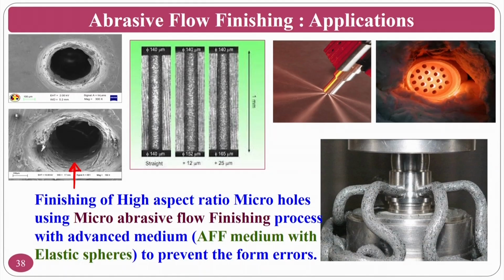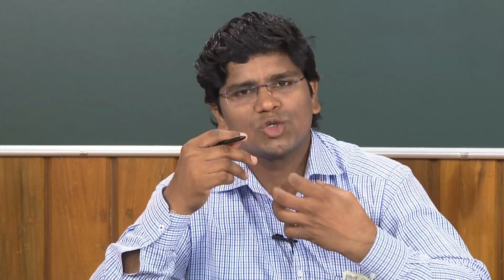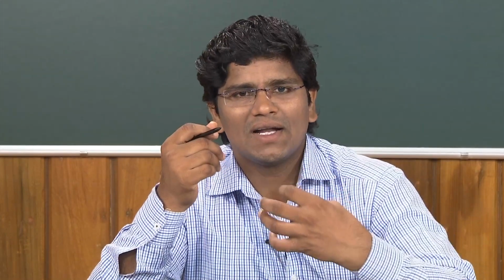So, this is a laser beam machined surface. You can see the recast layer. In laser beam machining, melting and evaporation are normal phenomena. If the material is unable to be removed, by virtue of the atmospheric gases or the laser assisted machining processes like air assistance, the molten material will stay there in the form of a layer, that is called a recast layer.